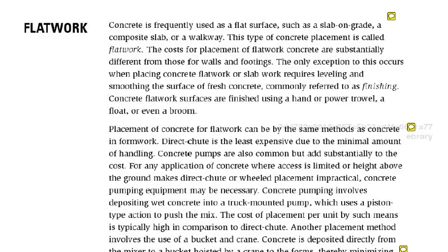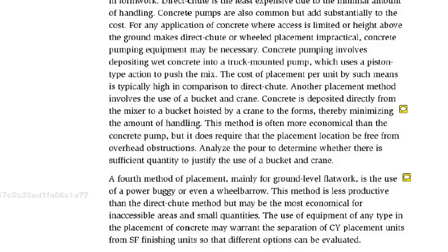So you're going to finish the surface. You're going to use trowels and brooms or stamps. One of the things that you can do is color any concrete or stain it, and you have to read the specifications to see what you're going to do. When you're looking at moving the concrete and doing flat work, there are different ways of placing the concrete in the edge forms that you're going to make.